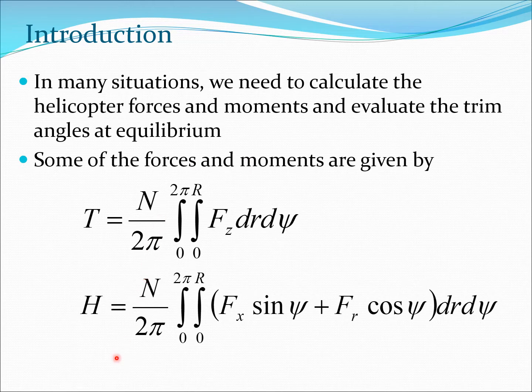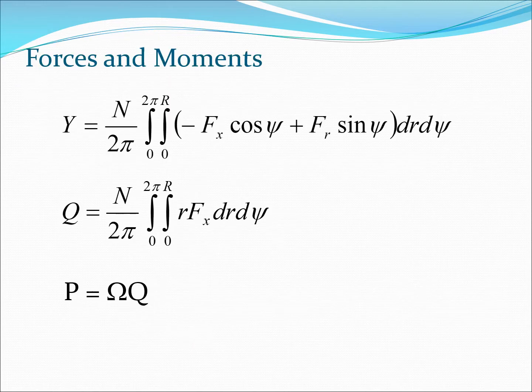Now similarly you obtain the H force in terms of Fx and Fr, and again the integration is performed with respect to r and with respect to psi. So these forces can be obtained. The Y force can be obtained using this equation here, and the rotor torque can be obtained using this equation, and then finally from the rotor torque we can obtain the power required. So essentially these are some of the mean forces which are acting on the rotor.